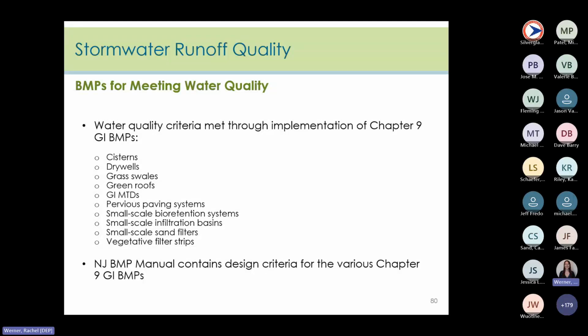I also think an important distinction for grass swales needs to be made because I saw a lot of people get this wrong on quiz 2, actually. So in general, there are 2 types of grass swales, right? Those being used as a BMP per Chapter 9.3, meaning you can use it for water quality control, and those not being used as a BMP.